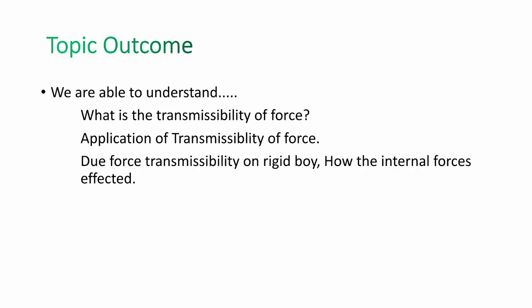So from the discussion, what is the outcome, what did we learn, and how can we think about this transmissibility of forces? We are now able to understand what the transmissibility of a force is. Without changing the equilibrium position of a body or the motion of a body, we can move the force from one point to another point in the same line of action of the force. Then we can say that is the transmissibility of the force.